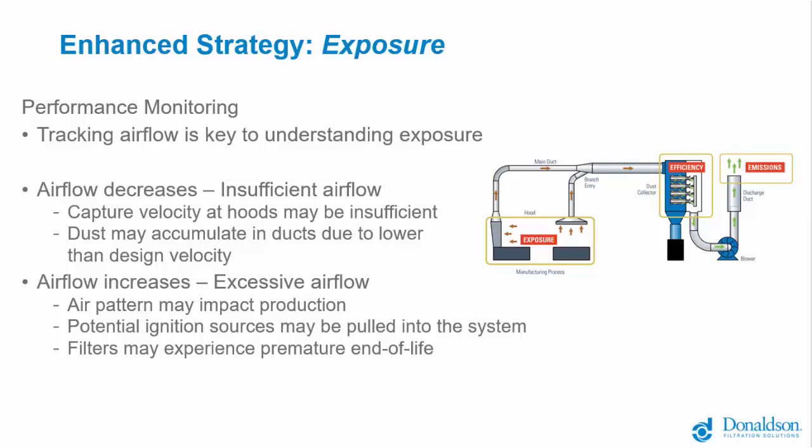And the excessive airflow can also cause particulate to hit the filters at an excessive speed, which causes it to embed in the filters. And that's going to cause premature filter end of life because they can no longer be cleaned with the compressed air.